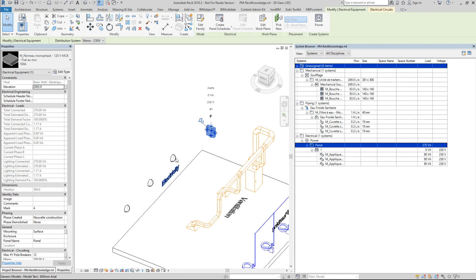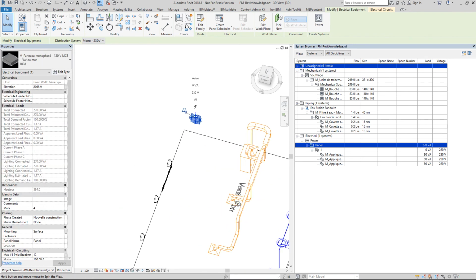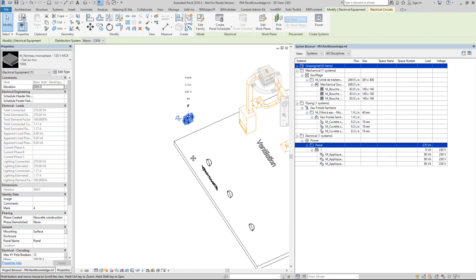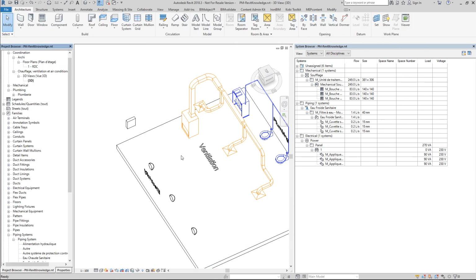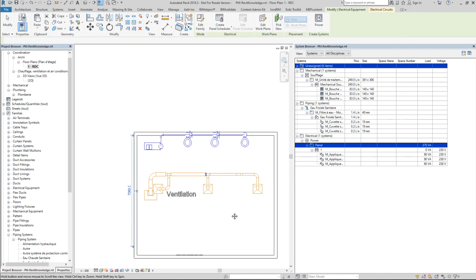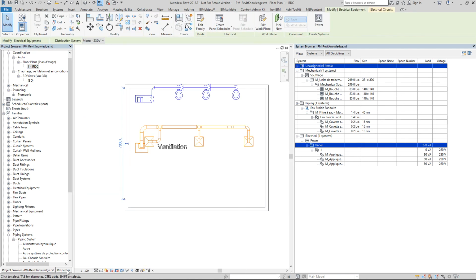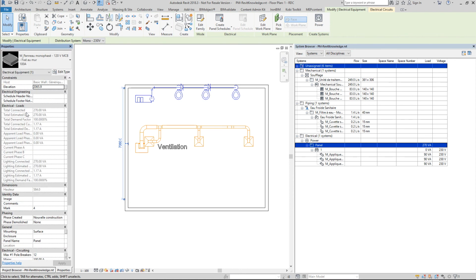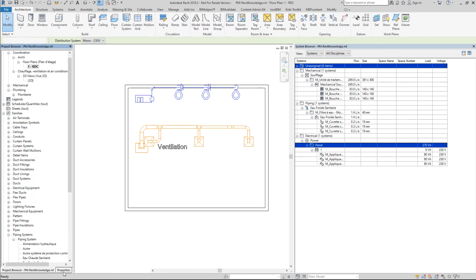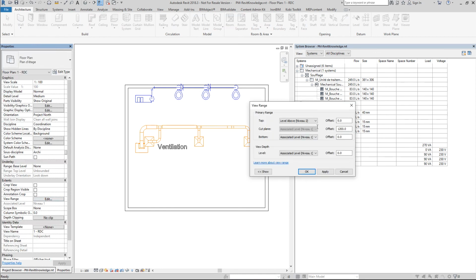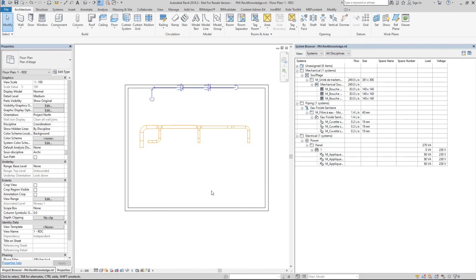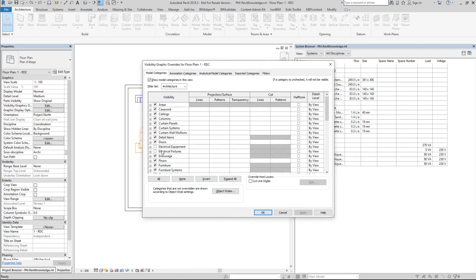Now that I did this, I can do some wiring. Well, wiring isn't really a 3D thing like you can see here. It's mostly in 2D, and it's mostly symbol lines. So here I go in plan view, and oh, I do not see my lights. Okay, maybe it's a view range thing. Okay, maybe 240 or not. No. Maybe a visibility graphics thing.